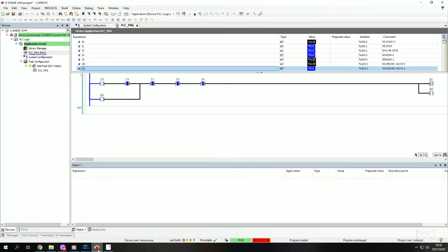If 3 bottles are present, the retracted end position, the diverting cylinder's piston rod is advanced. The bottles are diverted and transported to a second conveyor belt. The sequence is stopped by pressing a second push button.